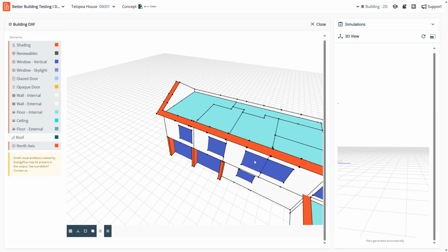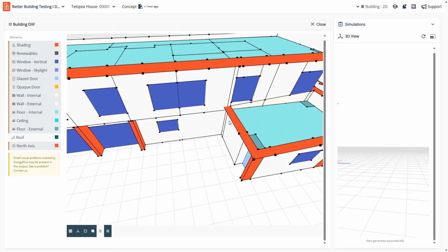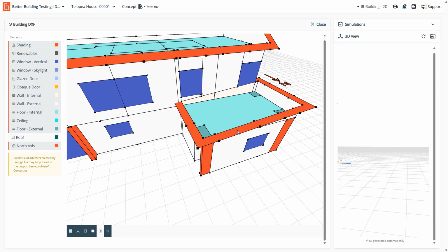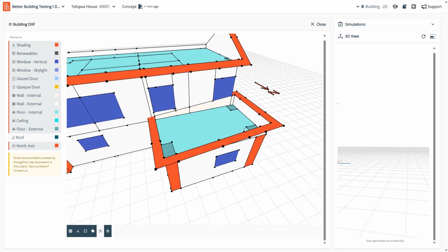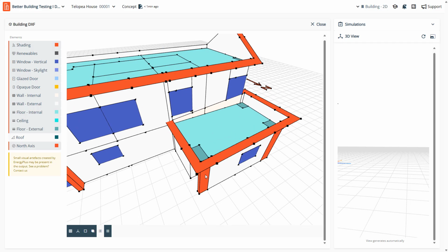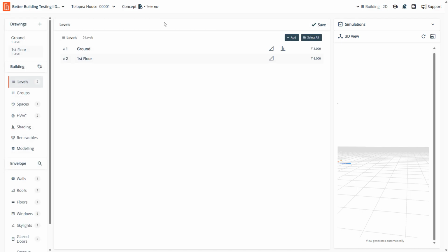And this is an important detail, particularly for residential homes, is that we often have different types of roof systems. We have warm roof systems where the insulation is at the roof line, and we have cold roof systems such as these examples. So I want to convert this room so effectively the insulation is projected to the roof line. This is how to do it.